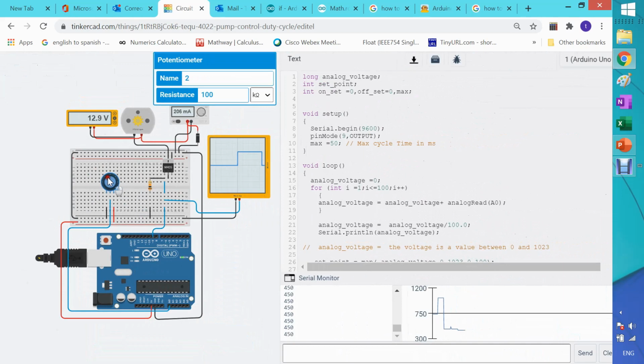Sometimes you have to increase the picture a little bit. There we go. See, adjusting pretty much to a value of 123, and so the motor is going full on, but then quickly shuts off. So that's what's happening, and that's why you see the voltage jumping. But it's controlling the motor in the end. I mean, you need some kind of inertia here. There's something here that spins, but when something is attached to it and it keeps spinning, it will not be this jumpy.